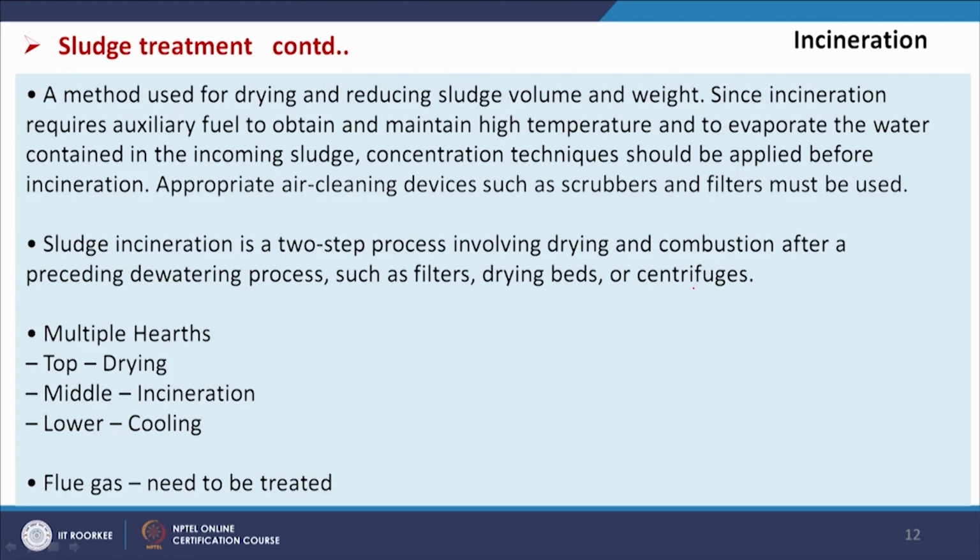In this process the incinerator may be of multiple hearths, with drying at the top, then incineration in the middle and cooling in the lower part. Auxiliary fuel is used, so flue gas is generated that needs to be treated.